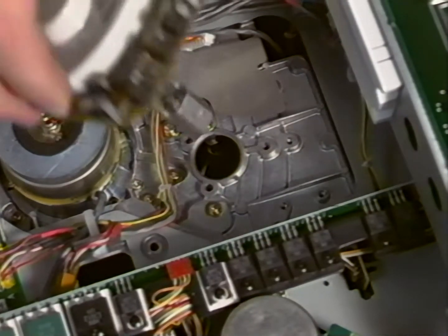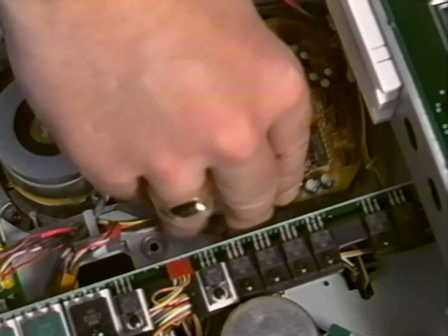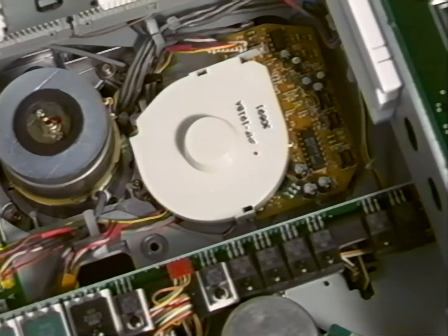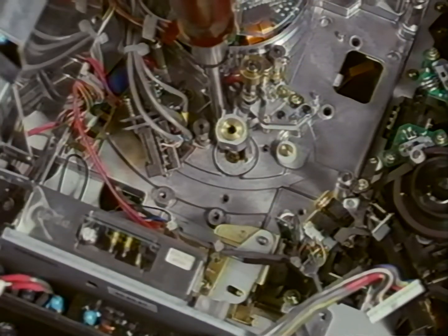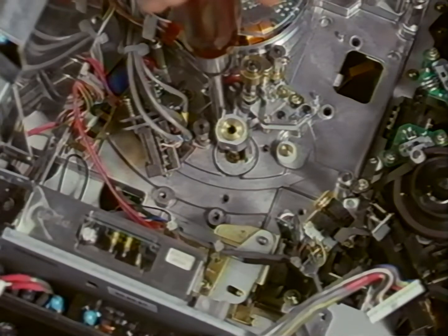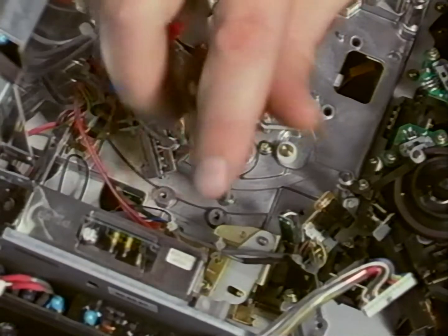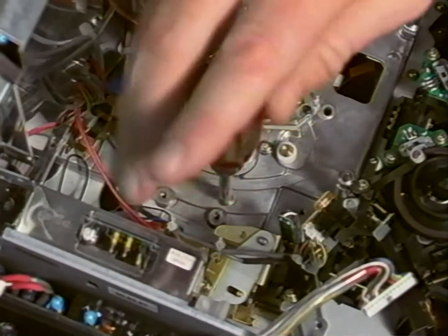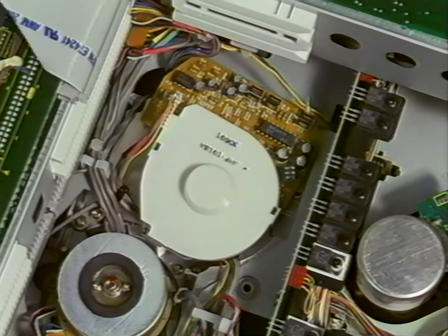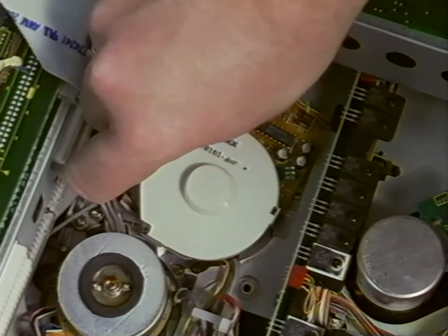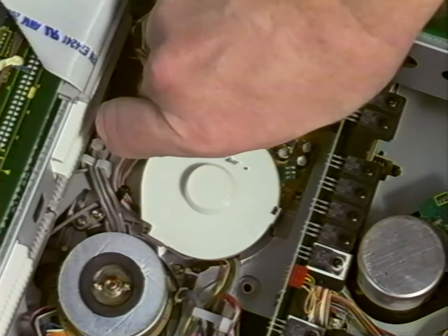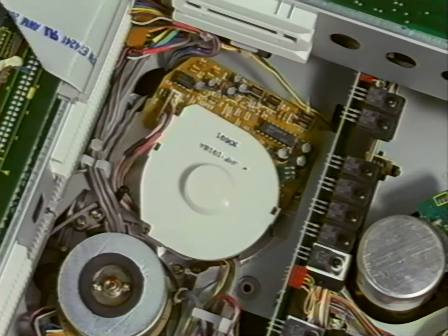Here it shows the installation of the capstan. Reinstall the capstan from the bottom of the machine. Secure the three fixing screws from the top of the chassis and connect and redress the wire harness. For the adjustment procedure, see Section 523 under Replacement of the Capstan Motor in the Service Manual.